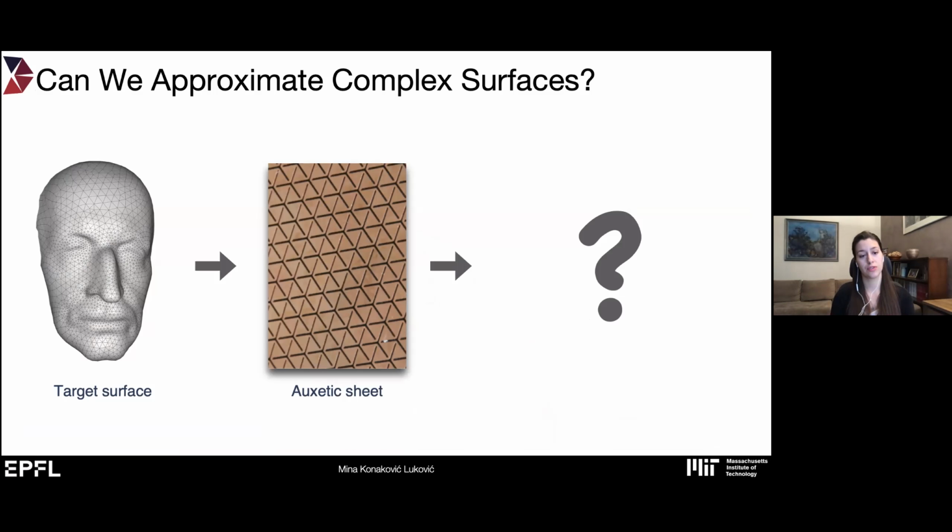And for the purpose of mathematics and controlling it in the algorithm, we abstract it in the form of a triangular linkage, a regular triangular linkage that has this so-called Kagome lattice, where on the most left-hand side, it's just a set of equilateral triangles. Then when you start opening it, it forms this hexagonal opening that is the most right picture on the bottom. And that's the farthest it can go in this configuration.